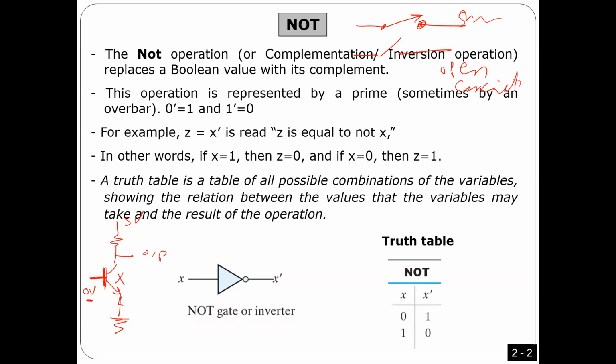Because the transistor is off, there is no current this way. And because of that, this circuit looks like an open circuit. That's why when you take the voltage here, you find the voltage is 5 volt. So when the input was 0 volt, the switch is off, and I got 5 volts. Is that okay? Again, I just want to give you some idea how we can do these crazy things. It's just an idea, so I'm not asking you to examine anything.